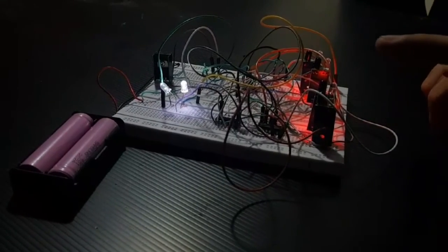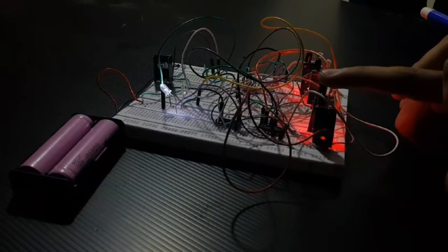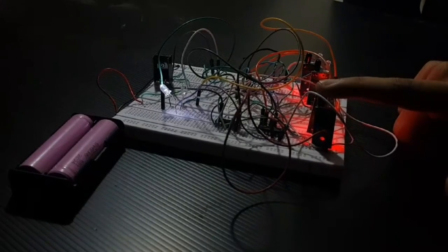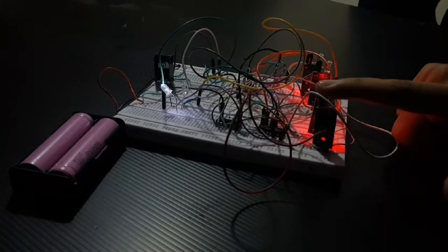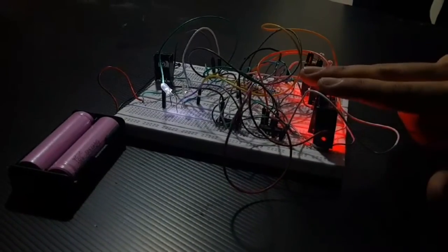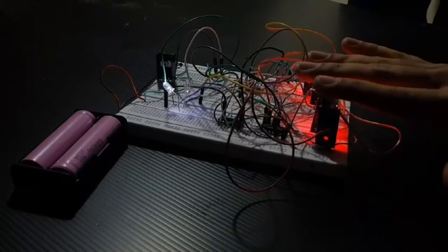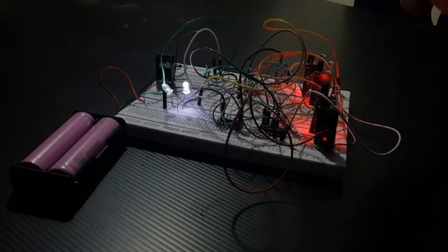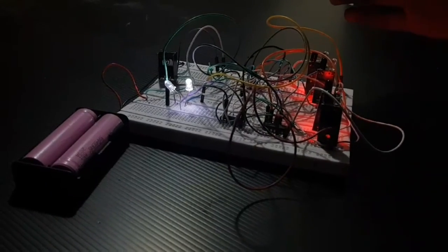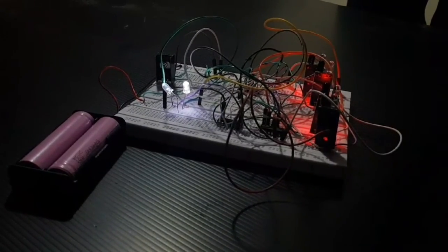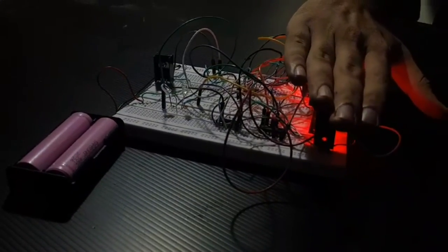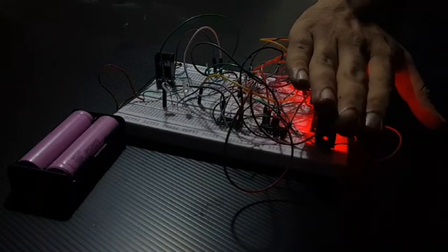Alternatively, when the right sensor is sensing a black line, then the right motor must turn off and the left motor must be on so that it takes a turn. Similar cases are two right sensors and all three right sensors. In the last case, when all the sensors sense a black line, then the motors must turn off and the robot should stop.